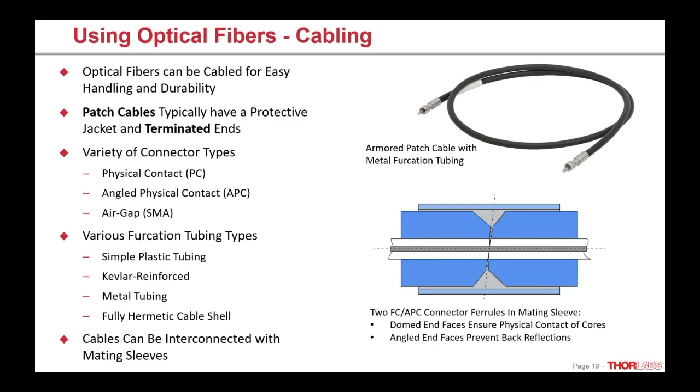Once we have nice end faces, we can take it a step further and build the fiber into what we call a patch cable. So this is like a whole package where we have terminated, polished ends and then some sort of protective tubing in the middle. And the fiber is completely encapsulated and it makes it really easy to handle and work with.